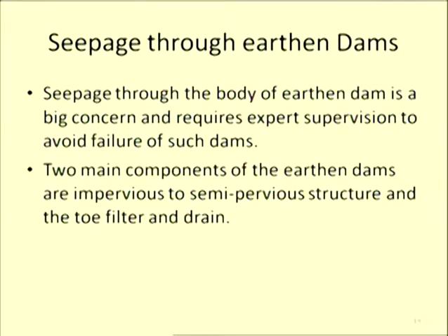If a dam fails, then it causes submergence of a large area, large irrigation fields, and also many times towns and villages come under submergence. So that situation should not occur. We should be very cautious while designing an earthen dam. We should do all scientific analysis before picking up a particular type of soil and deciding its dimensions, compaction method, and compaction technology used in it.